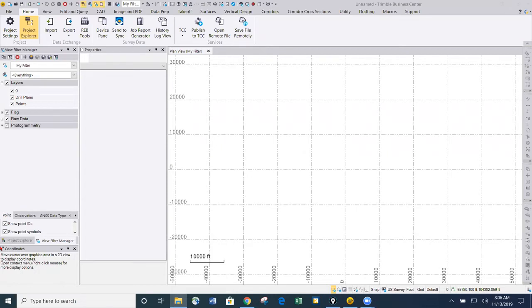but this now for site models. So you can input, for instance, the cross slopes between things, the elevation differences between things. You can put in free slopes at a direction, or tilts to put things onto a tilted plane in a parking lot for things like islands. And the system will grow a three-dimensional model that's parametric and sequential. So if you want to make a change somewhere, you can make a change and it will ripple down through the rest of the model to build a 3D model.